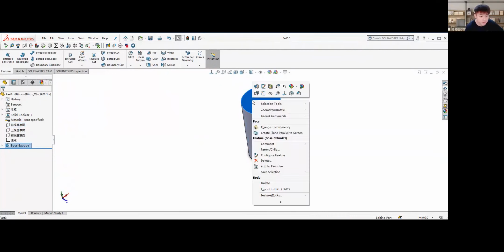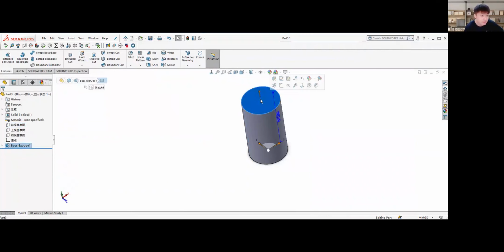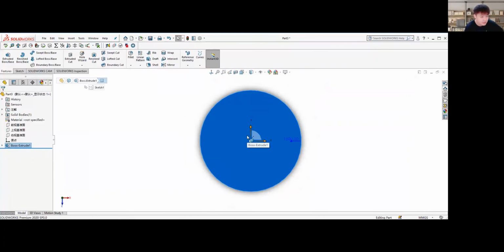Okay, we put the sketch on this face, the circle face, normal to this face. Laoshi, we can make a hole by making a circle and then press pulling it. We can make a circle in the middle and press pull it downwards so that we can make it hollow.